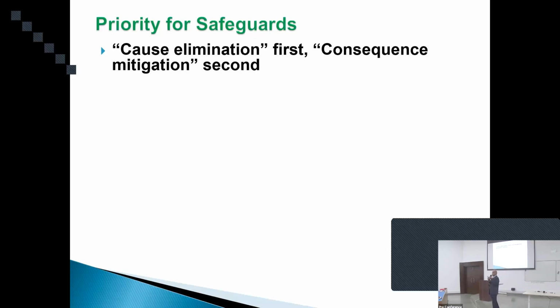There was a storage of 40 metric tons of methyl isocyanate in the plant, which was really not needed. Had they stored only 4 tons, that fatality would not have been this much. So that is why today, the concept of inherently safe design: don't store more than what you need.